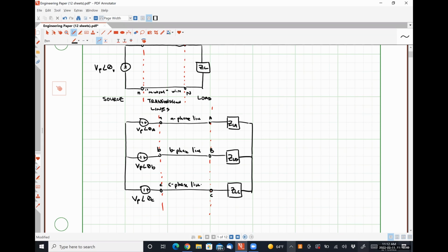causing mechanical damage. On a system like this, where the instantaneous power is constant, that means the torque is constant and vibrations are reduced. There is a very specific reason why the three-phase electric motors that we have in our power lab here at Louisiana Tech, which are literally some of them pre-World War II electric machines, still work with no problems whatsoever. And it's all because they run off of three-phase power.